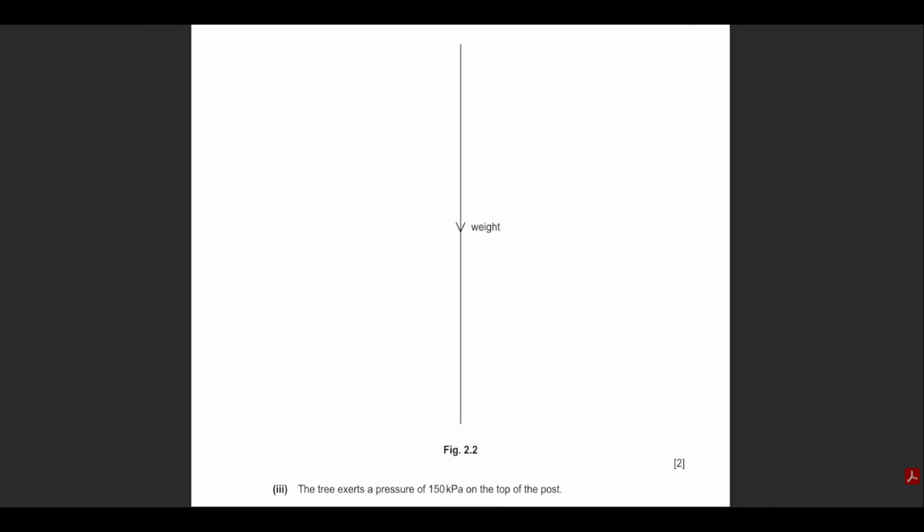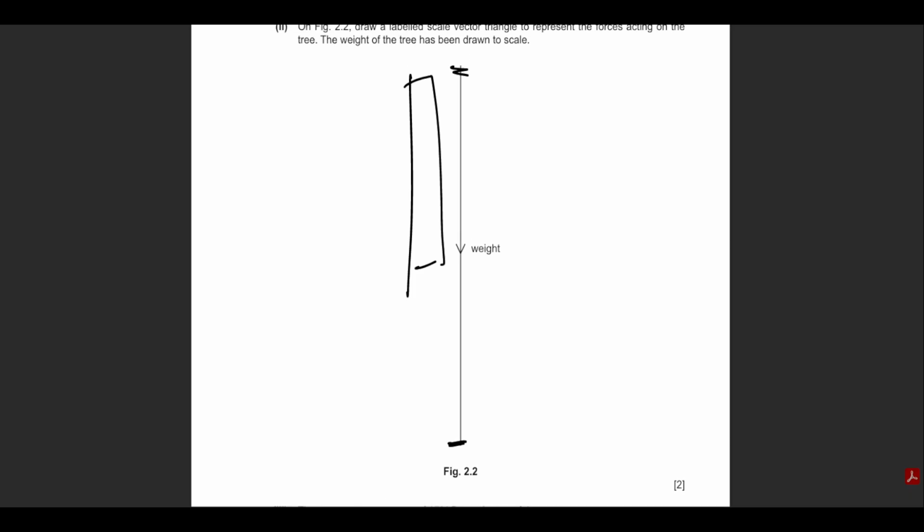So you were supposed to use a ruler and measure the whole length of the weight. Now, according to my calculations, this comes out as approximately, I think, 12.1 centimeters. It could be different for you because if you try to print this paper or you get this from any bookstore as printed past papers, there might be slight variation. But from my printing side, this was 12.1 centimeters long. And the weight, since this was 270 multiplied by 9.81, this was 2648 newtons. So that means that the scale of this diagram is actually 2648 newtons represented like this.